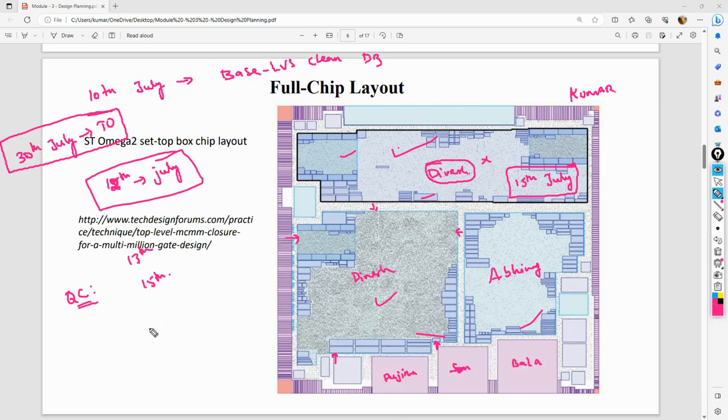Now this is the time where we do your full chip PV, full chip STA, and then full chip IR, and then full chip flat LEC, and all of that. So we need at least 20 days to get each of them run, provide feedback, fix them and get back. So though you might have closed your block, feedback keeps coming in from the top level, and you will have to keep rolling them in. So this is how people actually work. Until you tape out the chip, nobody is going to be free.